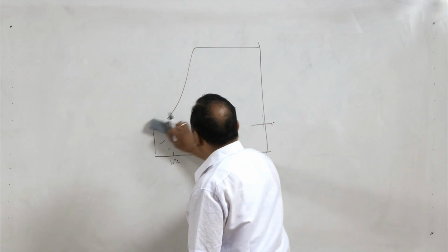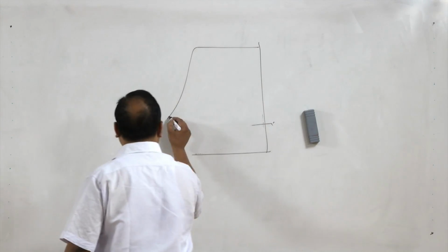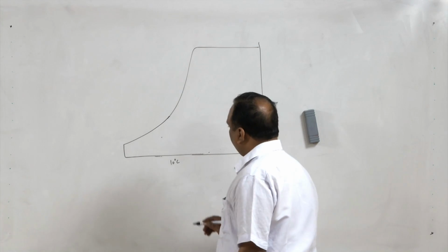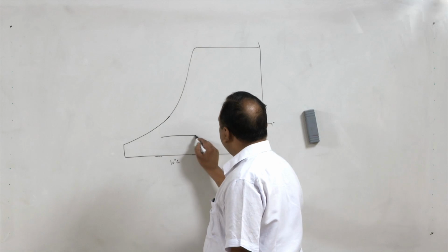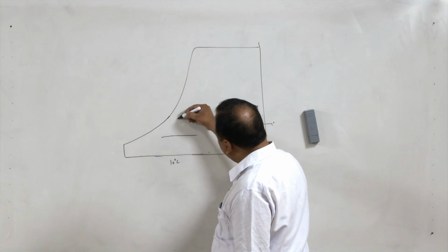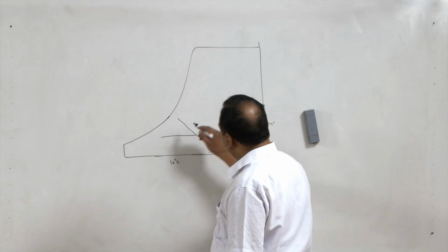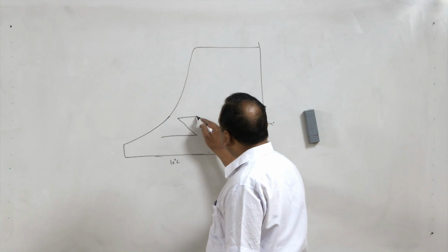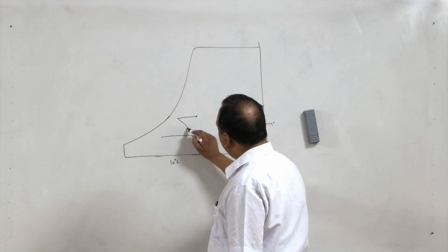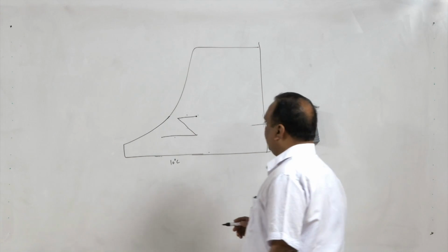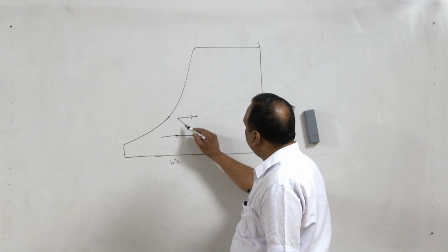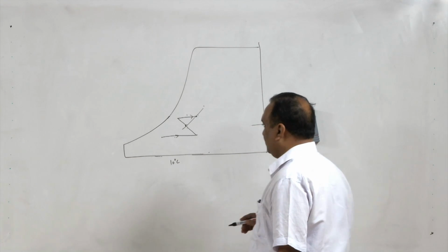Suppose this is the initial state. Initially we may heat, and then it is passed through the evaporative cooler and then again reheated. So, heating, evaporative cooling and then again heating. By following this path, we can attain the final state.